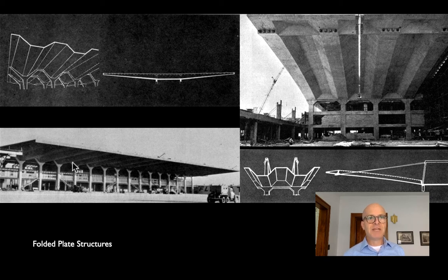done is they've taken a very, very thin shell of concrete, probably 2.5 to 3 inches thick, and they've arranged it with these deep folds, these kind of hexagonal folds, so that if you turn the hangar on its side and look at it in section, you can see what looks like a familiar double cantilever shape, right? Deep over the supports, tapering out to nothing over the ends.